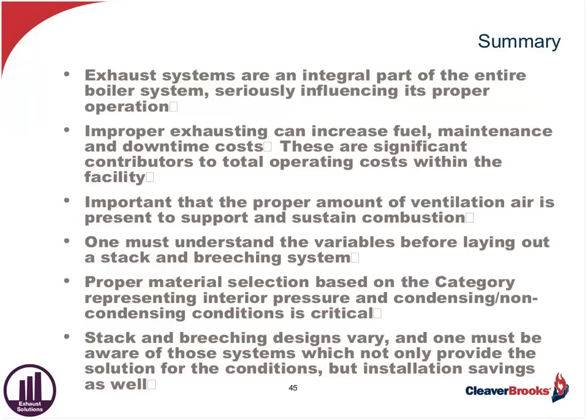Are you going through the calculations on the air coming in, the secondary air coming in for combustion? Obviously, there's resistance to flow there, so you're going to have to calculate the diameter of the combustion air duct so that we provide adequate air. Right. Correct. And then, obviously, the vent would be calculated the same as though it was not sealed combustion.